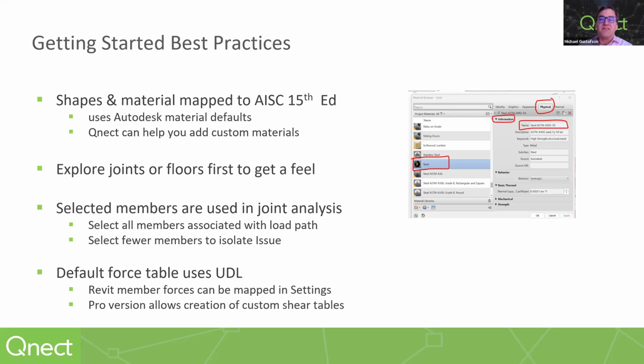And that means we're very sticky on things like HSS, right? HSS rectangular rounds cannot be A992, right? We're really following the AISC tables edition manual there on what the materials are. So that's the first thing to be cognizant of, and maybe require some interaction with us as you do your trials or explore the tool.